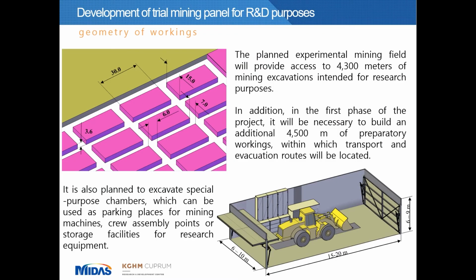Of course, due to the fact that the designed mining panel was not supposed to be an exploitation panel, it was necessary to take into account that we have to maintain the designed excavation for a longer period of time. Of course, we need to ensure stability for a few or even several years. Therefore, the designed dimensions of the pillars were much larger than the standard pillars used within the exploitation mining panels. The designed width of the pillars was about 15 meters, while the length of the pillars was about 30 meters.